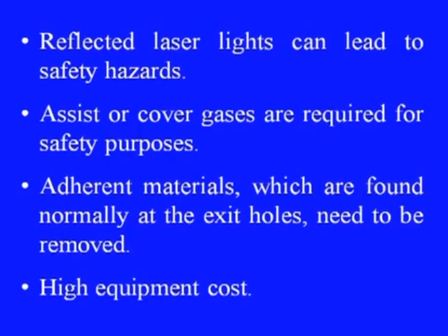The processing time in laser drilling is slower due to the trepanning action involved in it. The reflected laser lights can lead to safety hazards. Assist or cover gases are required for safety purposes.